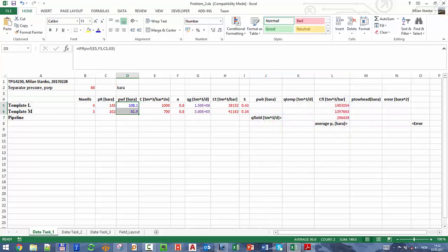Now, what happens if at any point you obtain a value error here? What does it mean? Well, it means that you have a square root of a negative number. That means that rate is physically impossible, because you would need a pressure that is negative, and that's not physically possible. So if you already get a value error here, you can go to the reservoir engineer and say, no, you cannot produce that rate. Your IPR doesn't let you produce that rate.